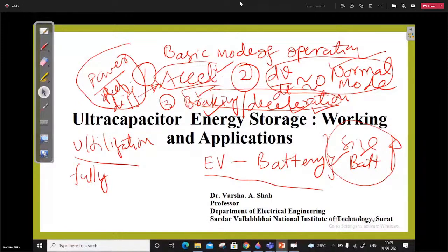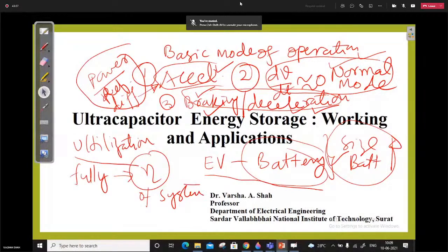So in that case, we are keeping the maximum amount of the battery power idle, we are not utilizing it. And that is always true with any electric motor. If you need to operate a load of, let's say, 5 HP, and the size of your motor is 10 HP or 15 HP, you can imagine at what efficiency your motor is operating.